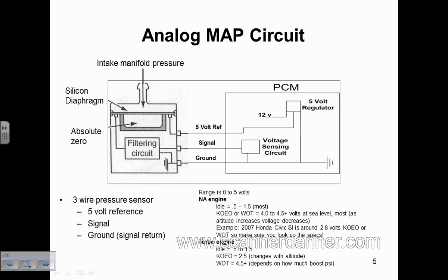They look good. What would be the next thing? You haven't even started the car yet. Look at your throttle position sensor. Make sure you're under a volt. Why are we using that under a volt number? That's what all of the cars operate at. Under a volt at idle, and it should increase as we open and close the throttle. So can we do some quick tests on the TPS on any car on the road? Now, you don't know the exact spec, but can we look at ballpark numbers? And the answer is yes.